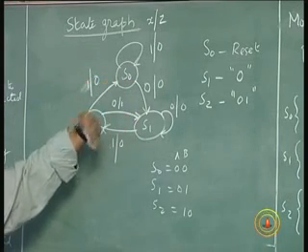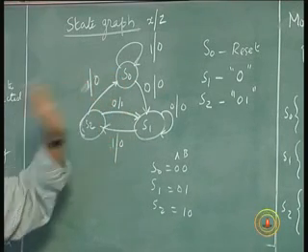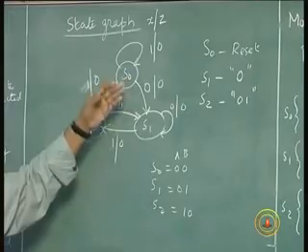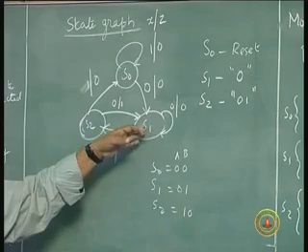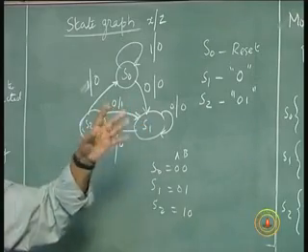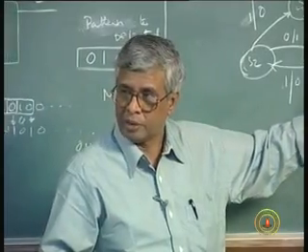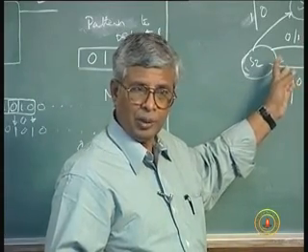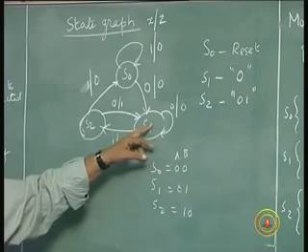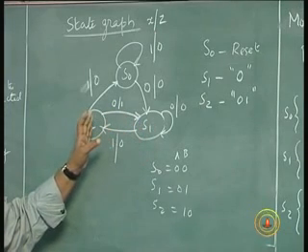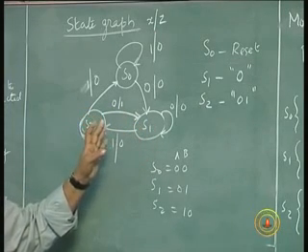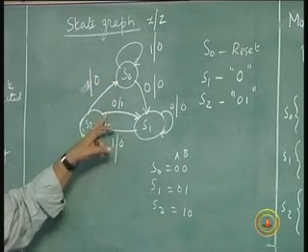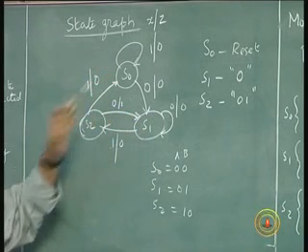The circuit can exist in 3 states. In the first state it is waiting for the bit to come. The bit can be 1 or 0. If it is a 1, there is no use for it. If it is a 0, it goes and remembers that. If it is a 0 there again, the same 0 has to be remembered, so there is no need to go to a new state. It continues to be in the same state. So 1 comes, go to another state where it remembers 0, 1. In this, if a 0 comes, you have completed the pattern, but remember the last 0. On the other hand, if a 1 comes, there is no use for any of them, because 0, 1, 1 has no meaning, because again you have to start all over again. You have to go here. And no output except in this case when 0, 1, 0 is completed. In all other states the output is 0.